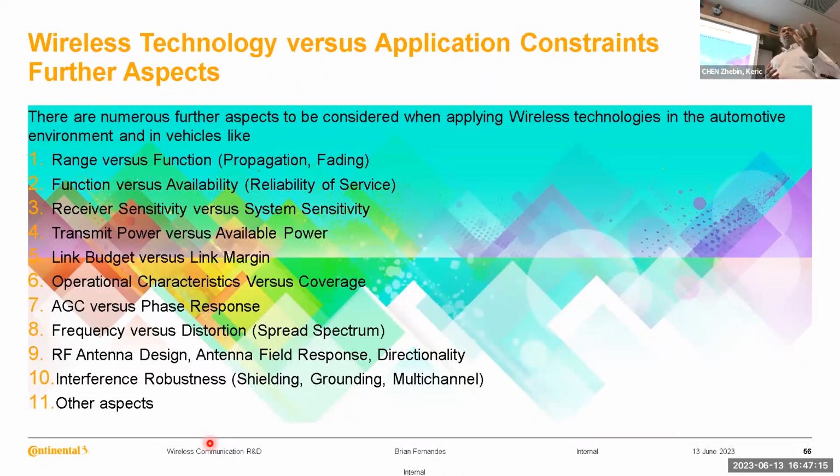So when you take a particular receiver with a particular sensitivity and actually place it in a product, you will see that the system sensitivity starts to degrade because of maybe the grounding is different, the board is limited in terms of its grounding, in terms of the interference from nearby electronics. So having a perfect system using the receiver sensitivity data may not be in reality possible. So you have to consider the system sensitivity effects.